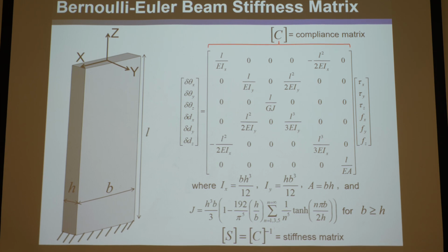Okay, and now by the way, these equations will only hold true when this is truly acting as a beam, meaning its length is something up to the order of like 10 times longer than its B and H.